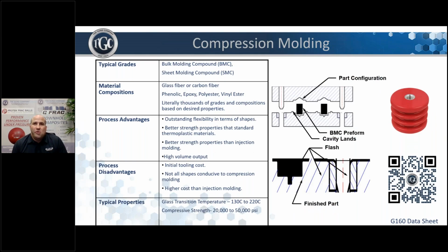First, we'll start with probably one of the most popular composites for downhole tools, those made from compression mold. There are many benefits to compression mold. High property strengths with random fiber orientation allow for really high performance parts. There are many glass options and systems out there, literally thousands to choose from. With longer fiber systems, you can provide extra strength. Compression molding allows for a high part output, given you select the right cavitation for your mold to meet your demand.